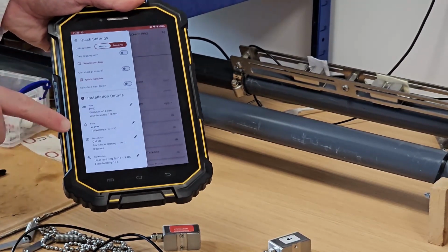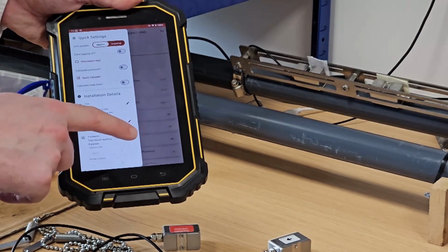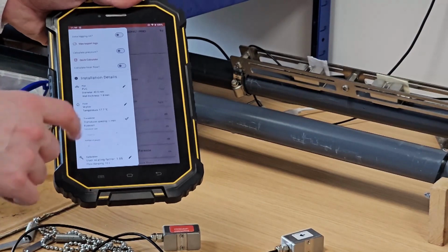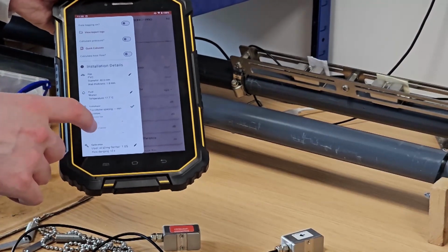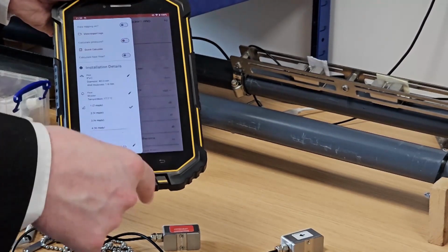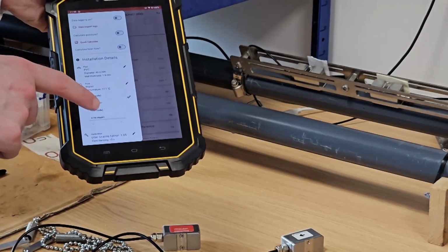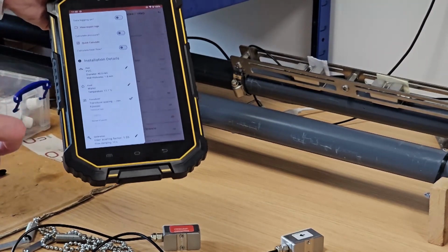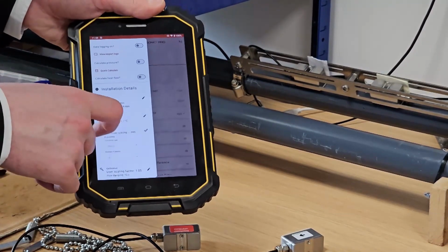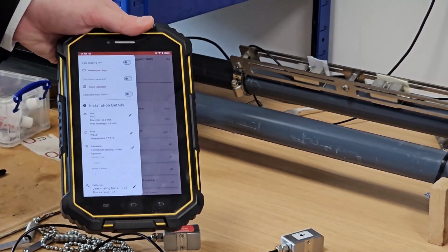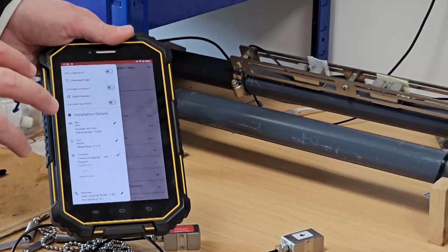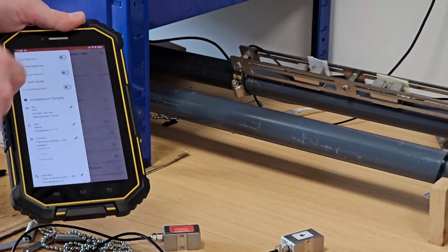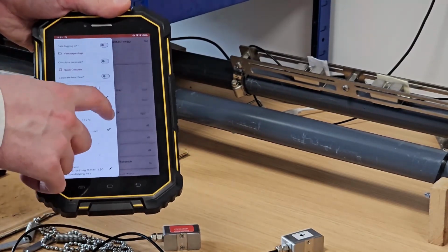And then for our transducer, you can see we have the DM10 sensors, which are our standard sensors, which I will be using for the demonstration, and our mounting method or number of passes, which I have set to 8, means 8 passes of the ultrasound through the pipe. We can choose any value from 1 to 12 for this. I'll stick with 8 for this particular demonstration. And we also have here a transducer spacing field, which isn't user input. That will be read from the sensor once all of these parameters have been written, and that will tell you how far apart your upstream and downstream transducers should be placed.